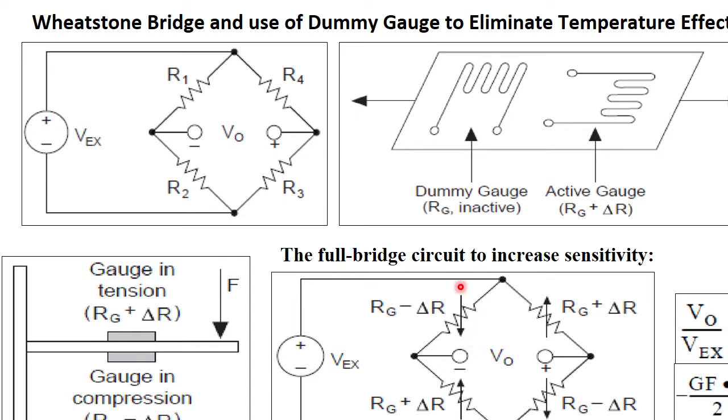So for a full bridge in such orientation, what would be the value of strain here? This would be 1.3 times the earlier results, taking Poisson's ratio as 0.3. Or if Poisson's ratio is not known, we will get the ratio of the two measurements, first one without the transverse gauge and the second one with the transverse gauge, and that ratio is proportional to the Poisson's ratio of this material.